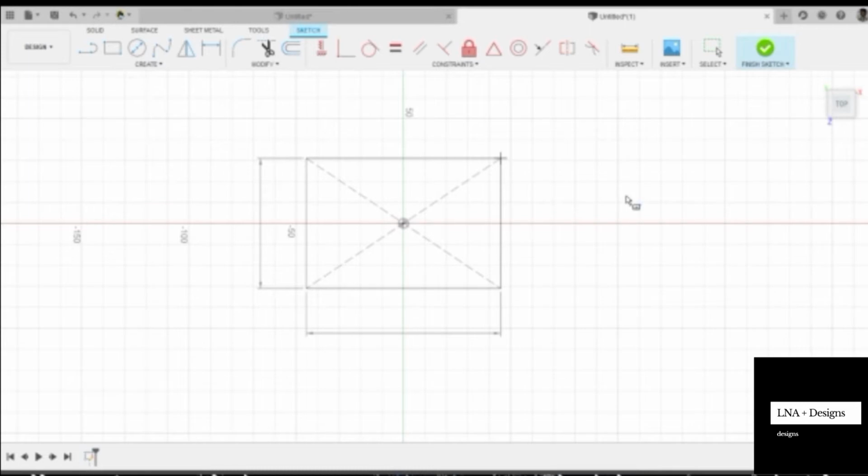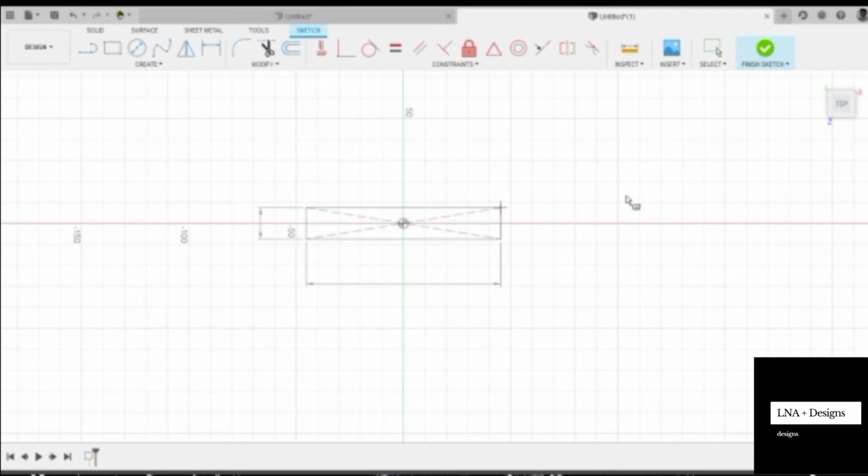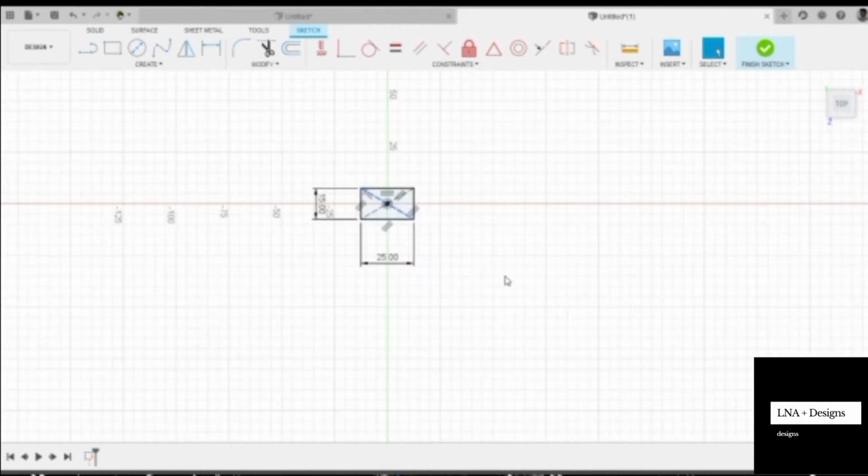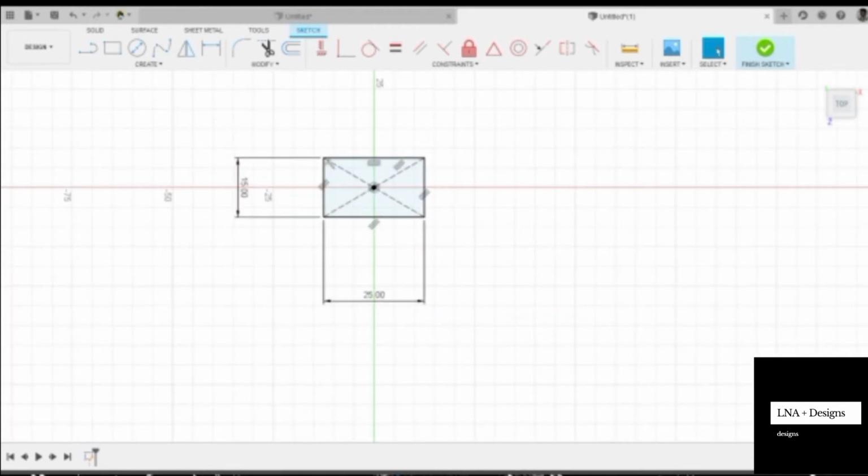We are going to take center and set it up. It is going to have a width of 15 mm, and I'm going to hit tab so that the cursor will shift to this dialog box. Tab. This is going to have 25. Yeah, perfect.